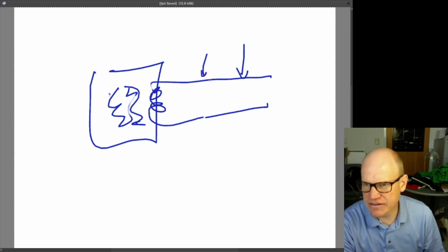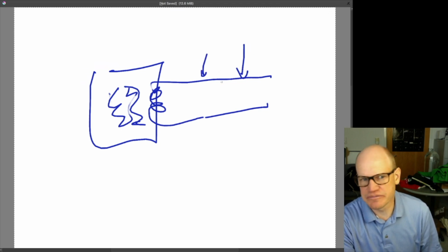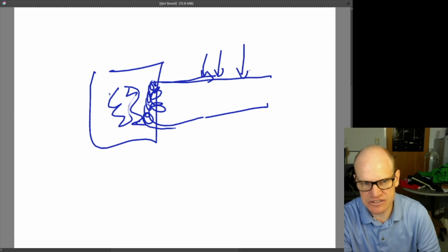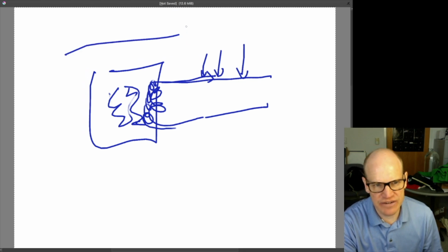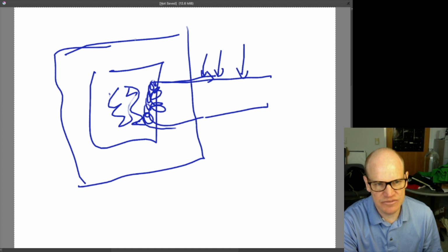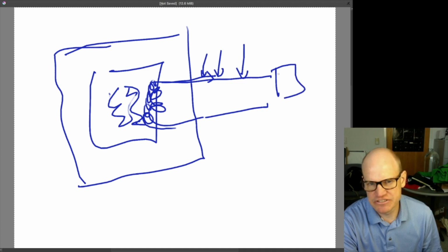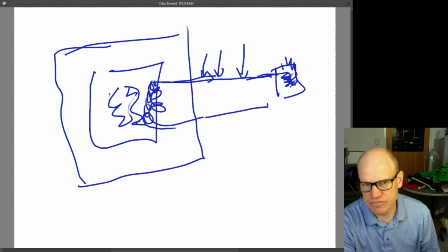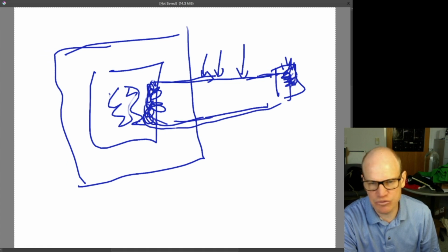This one doesn't have any radioactive materials in it. So you bring it into the reactor, you warm it up in the reactor, and then you send this out. And this can be a totally benign substance. And so you only have to worry about this part of the system, and then you have your, say, paper mill over here, and you just bring the nuclear heat in here and then have another heat exchanger. You blow air across it or whatever it takes to extract the heat from this pipe into your plant, and then you send it back in here and have it warm up again in the reactor.